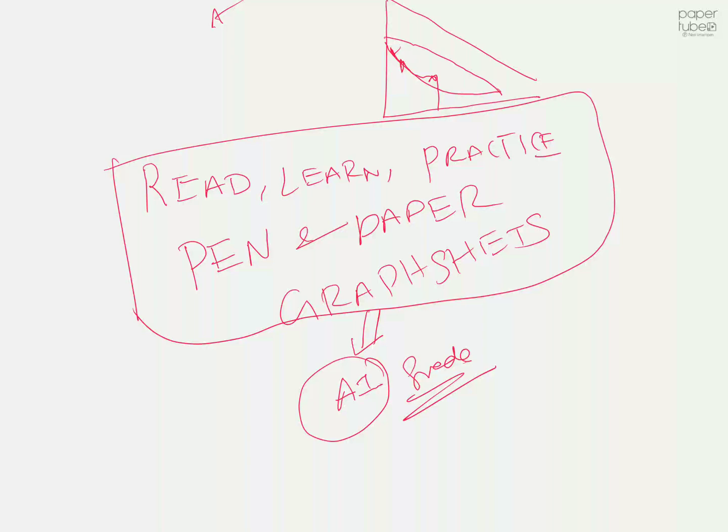I already said a few reasons, and there are a few other things. Normally, if you are doing anything at plant scale, like several thousand liters, compared with an experiment at lab scale, for example 1 gram of your product, obviously you can use maybe half a liter of solvent, throw the solvent away, and go for the next reaction with a fresh solvent. That's what I do in the lab. But in industries, when we are working with 10,000 or 30,000 liters, we have to find ways to recover the solvents.